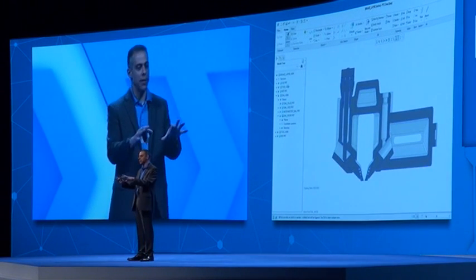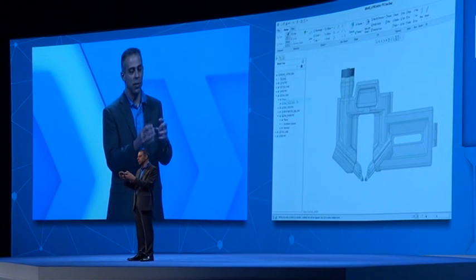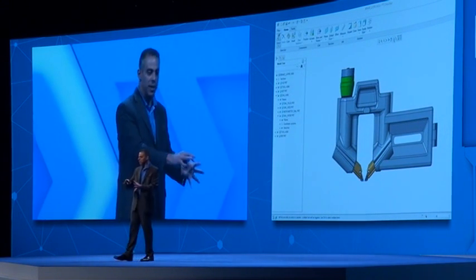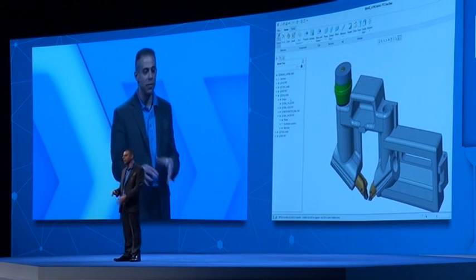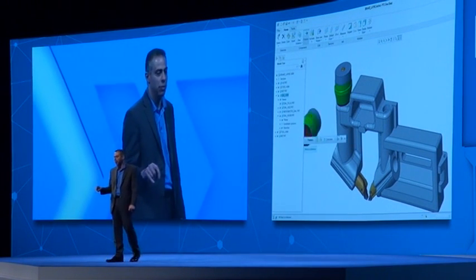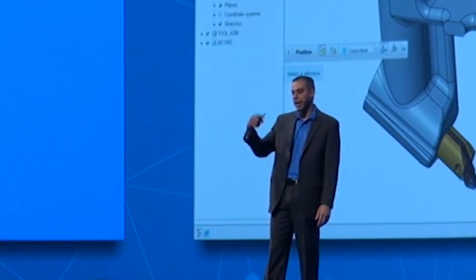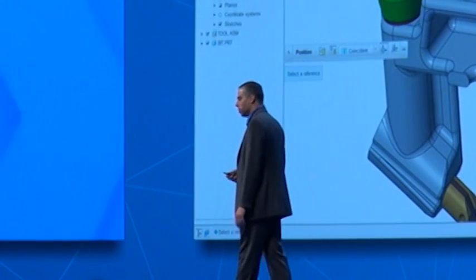And now that I've got this added sub-assembly with this new part in it, we have this nice capability called shared occurrence where I can repeat an existing component in my assembly. It's very simple. It's right there on the right mouse button in Creo Direct. And now I have it right there on the pointer, and I can assemble that in. Okay? So that's shared occurrence.